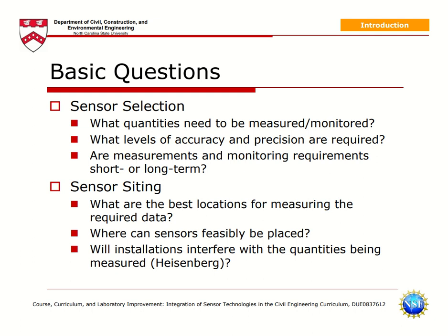Same way, if you are measuring the speed of a motor, let's say with a hall effect sensor, then what would be the perfect place to put that hall effect sensor? Right, close to the rotor, right? You cannot place it outside the motor and then expect it to measure the speed, can you? No, you cannot do that. So it is important to identify the best location for the measurement device for perfect or good measurement of required data.